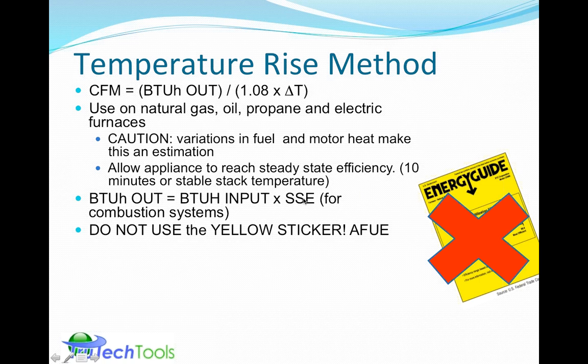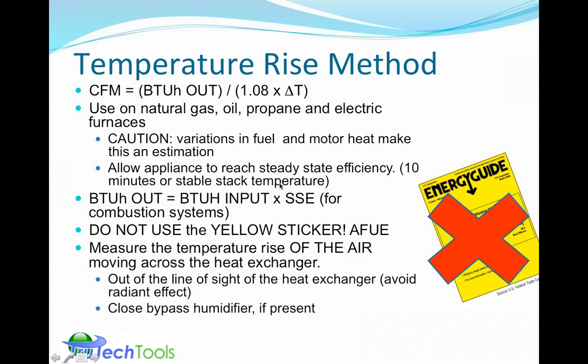So as you can see, this does get a little bit complex. If you really want to follow the letter of the law and do it correctly, you do have to be careful about motor heat, variations in fuel quality, and you also need a combustion analyzer to get that BTU input. Sort of a lot of work in order to get back around to the airflow measurement.